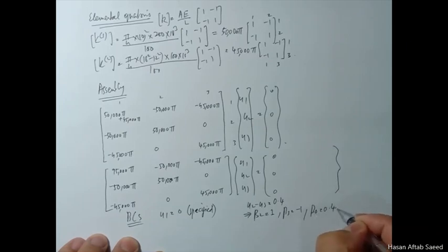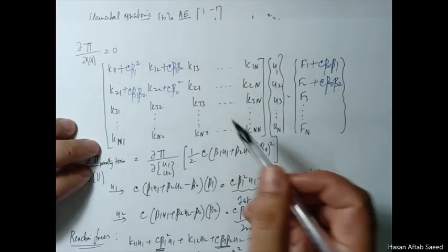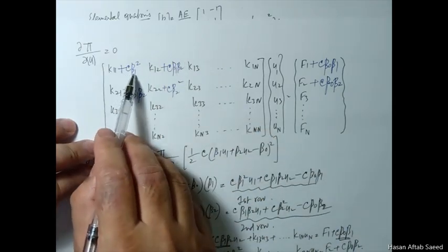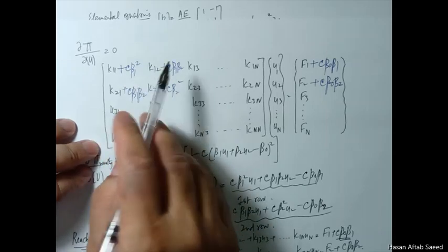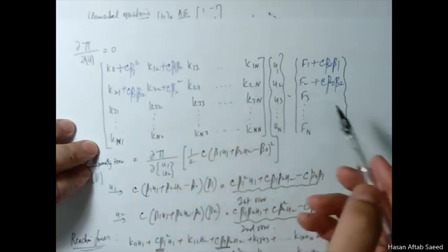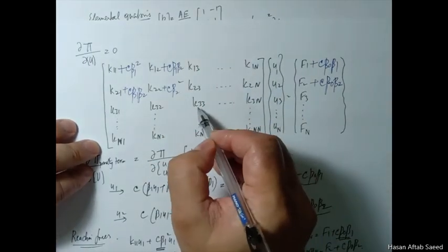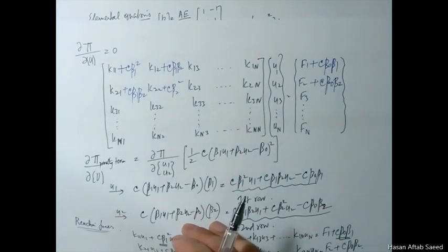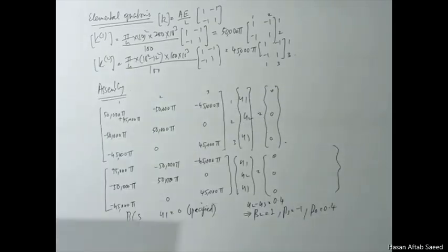Now recall from the development that we did when we were studying this multi-point constraint method, we have to apply this value, c beta 1 square here, but in this case instead of beta 1 we are going to use beta 2 and beta 3. So we apply on the diagonal term, and for the third element, u3, we apply on this diagonal term, but the thinking is the same. Just replace u1 and u2 by u2 and u3.